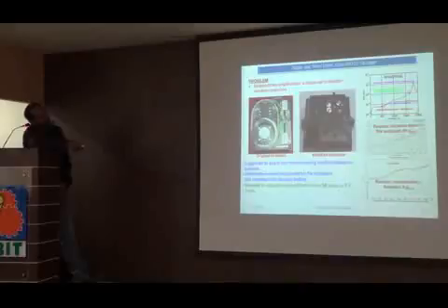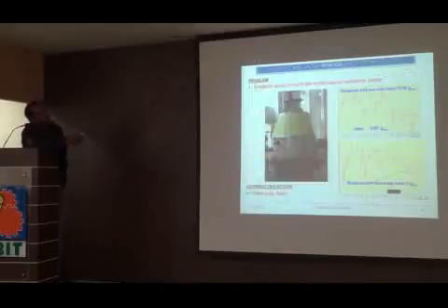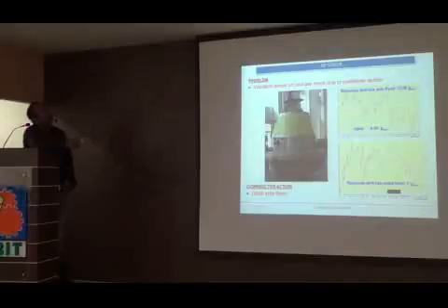So what we did was modify the mounting locations. This is how we have reduced it. And again there is one kind of electronic system which we call a seeker, a radio frequency seeker. Seeker is a critical element in the final stage target detection. This was again failing due to the higher input. Then we observed that we can change the boundary conditions of this structure so that the response can be reduced. So we changed from cantilever to fixed condition so that the response has come down.